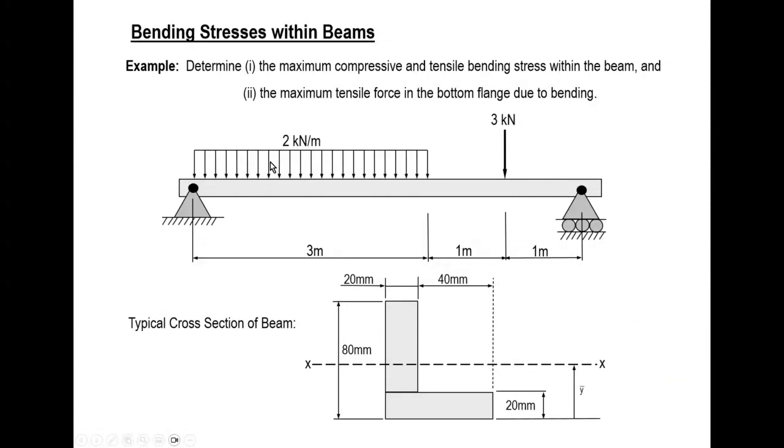In this problem, we would start with solving the internal forces. Before starting internal forces, I have to find out the reaction force. And from the reaction force, I should go through the bending moment diagram. And from the bending moment diagram, I find the maximum bending. And from maximum bending, we can go to the flexural formula and find the maximum stress at a certain critical point.